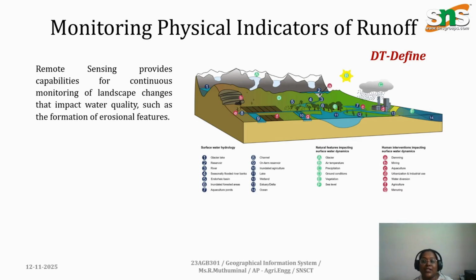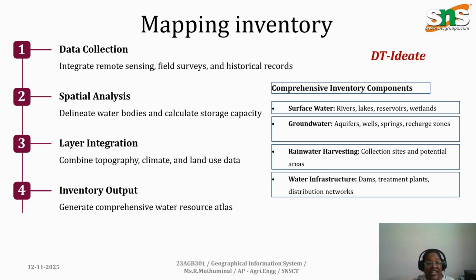In order to avoid these kinds of problems, we can provide a gully indicator. The gullies in sand and gravel exhibit a short V-shaped cross section, and the gullies in silt soil show a U-shaped cross section. Gullies in silt, clay and clayey soils tend to be long with gently rounded cross sections. If we identify the physical characteristics of the gully, obviously we can avoid the problems or the changes in the landscape. By mapping these erosion prone areas and monitoring the formation of gullies, water managers can prioritize intervention upstream to reduce sediment load and nutrient transport, which are critical components. So the main critical components like water quality assessment, vulnerable landscapes, erosion rates and erosion prone areas could be redefined. These are some things we have to take into consideration.